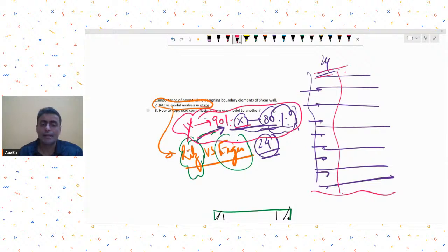So basically it helps you with your analysis time. Unnecessary modes which are neither contributing to the mass participation nor having any significant contribution otherwise will be ignored, and instead only the meaningful modes will be given. Meaningful mode means depending on what extraction you want. So this is called the RITS analysis. So RITS versus eigen, that is the basic meaning of it.